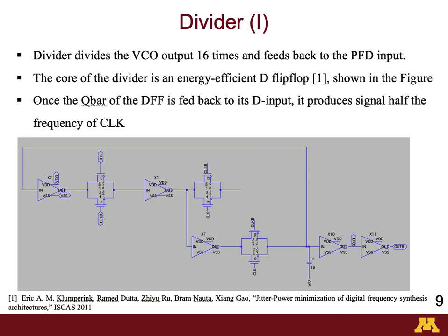Here, Professor Klumperink has shown that among all different D flip-flops in terms of power consumption as well as jitter reduction, the dynamic transmission gate based D flip-flops are the best. They do not consume any static power, they only consume dynamic power. And for our design, we are following this reference and following this energy efficient D flip-flop structure.